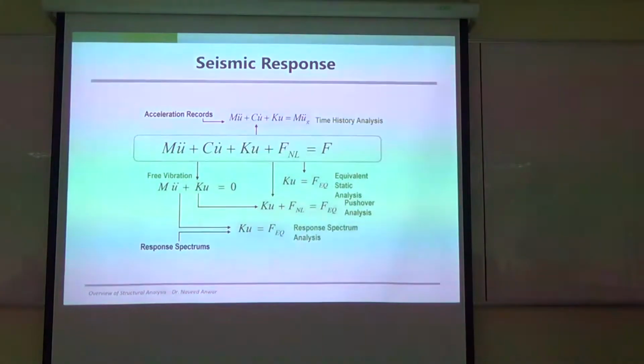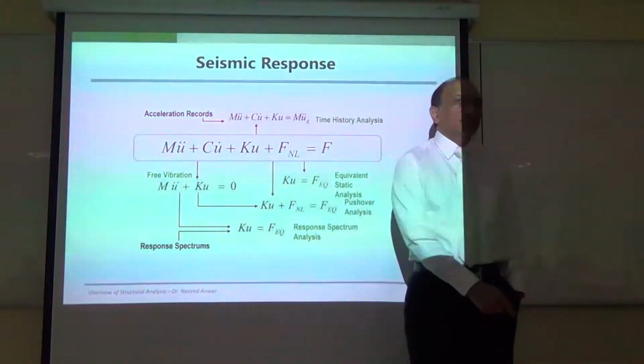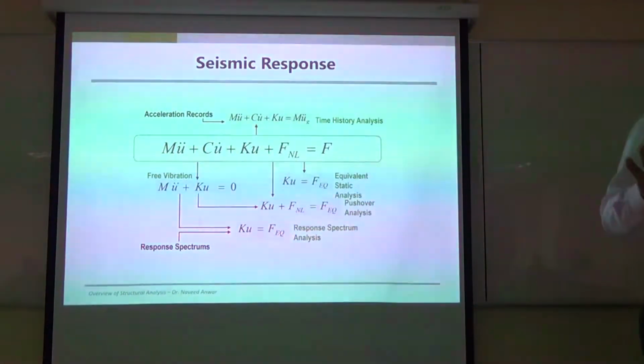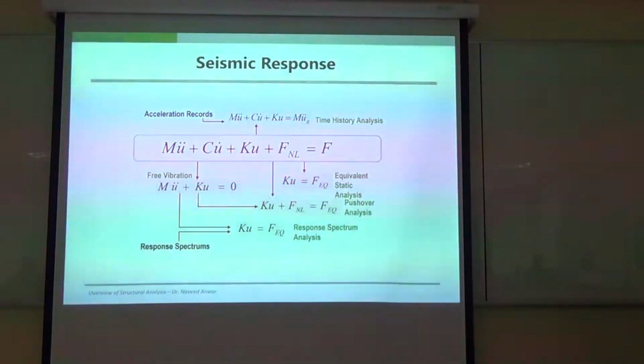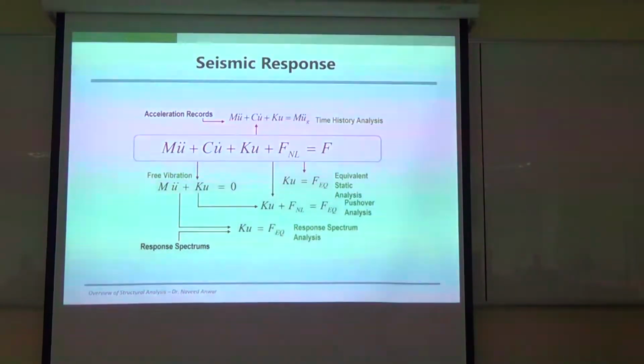We can also determine from the same equation, coming back to the equation, if you want to do the earthquake analysis, you can use that equation for all types of earthquake analysis. There are several types of earthquake analysis that you can do normally. A static force analysis, equivalent static analysis. You can do the response spectrum analysis. You can do a pushover analysis. You can do a nonlinear dynamic analysis. You can also do a linear dynamic analysis. So 5 types of analysis you can do for earthquake, each giving you completely different results.